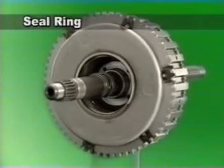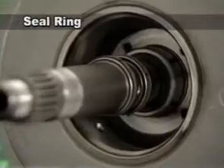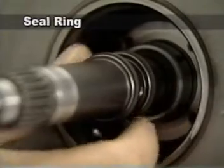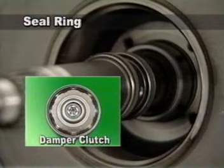First, check the appearance for damage of the 2 seal rings where the underdrive clutch of the input shaft is assembled. If damaged, oil leaks from the torque converter and release pressure of the damper clutch decreases. Then it might cause the damper clutch to malfunction.